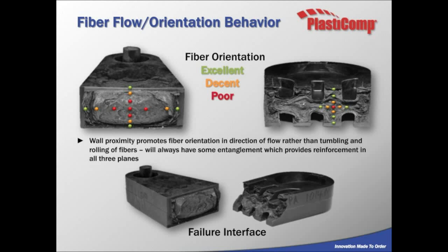We can see that the best fiber orientations are closer to the surface of the part. The closer you get to the center of the part, you get more poor fiber orientation. And the thicker the part is, the more volume that's getting poor fiber orientation through the cross-section.